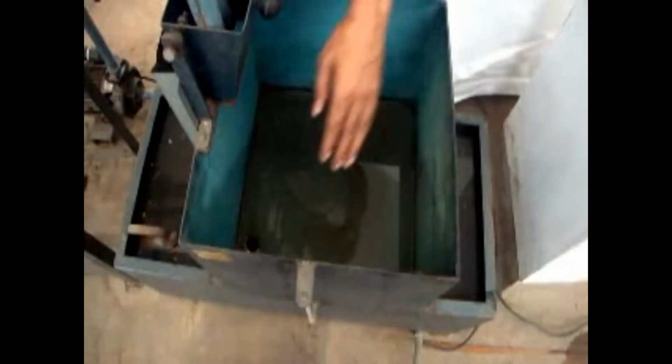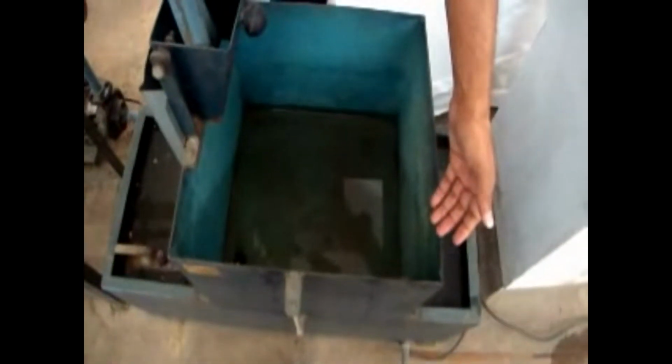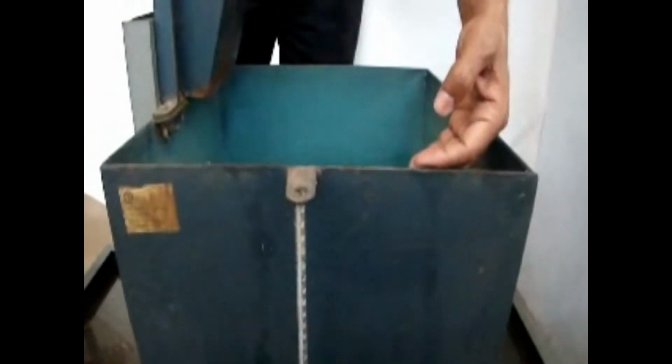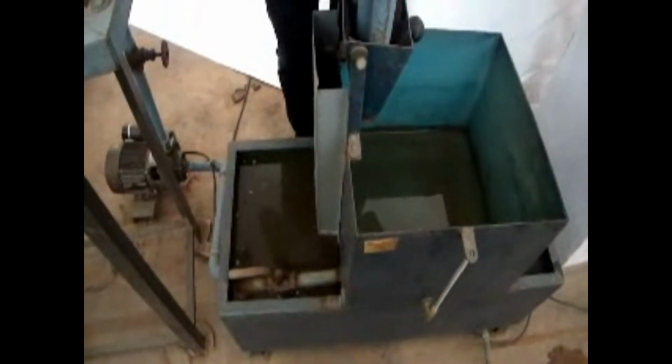The tank has a defined dimension, length and width, and we can find out how much head of water or discharge is collected in this tank per unit time, or simply time versus height. So volume versus time we can find out, or for a particular head or particular time we can measure the discharge that is coming out from these two.